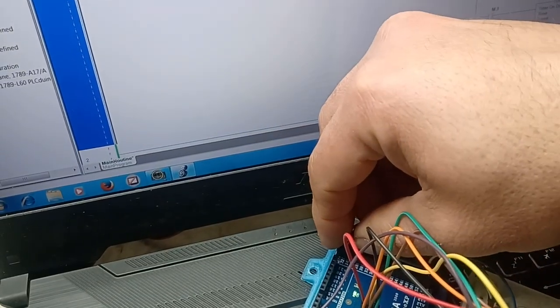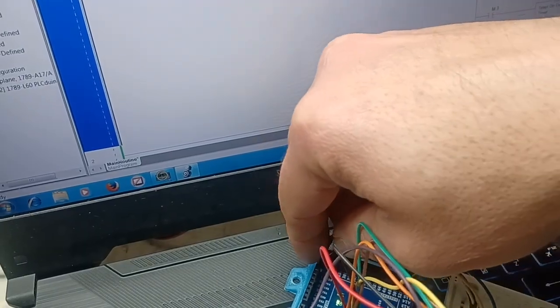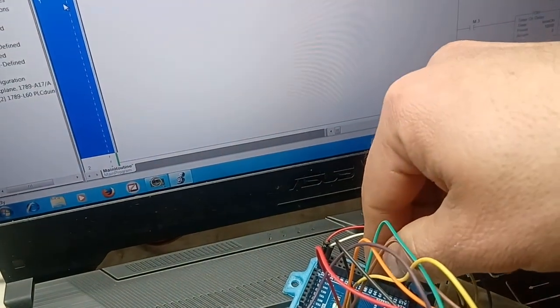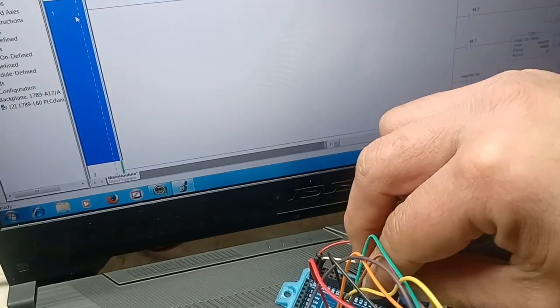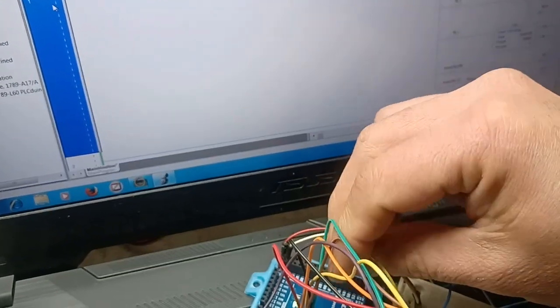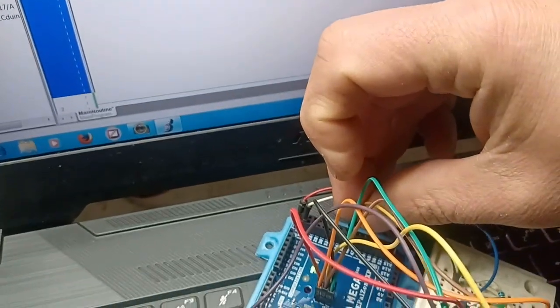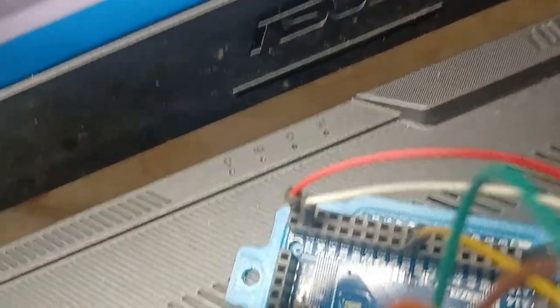Well, actually pin number 37. I'm going to change it to 22, which is the first bit in the input range. And I'm going to move the output to 38, which is the first in the output range. See if I can get that. I'm using one hand only. So I got both pins changed, right?